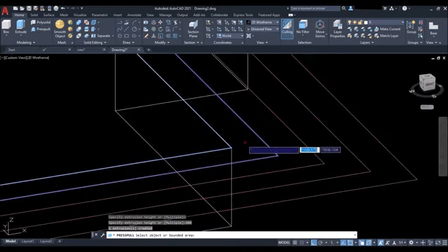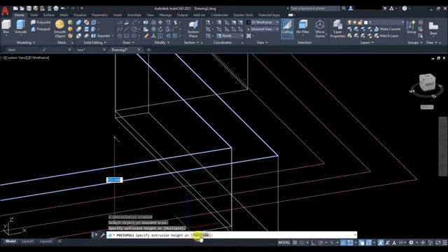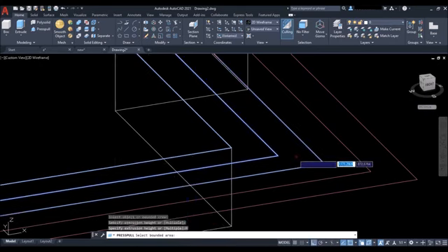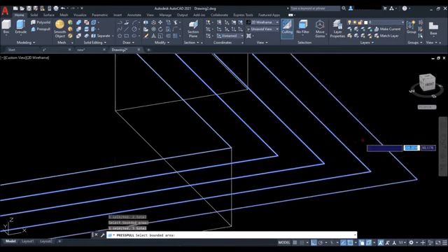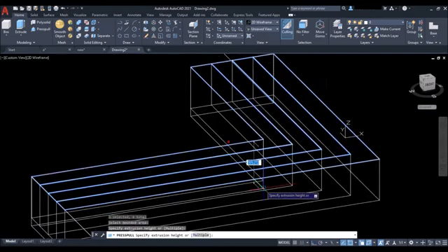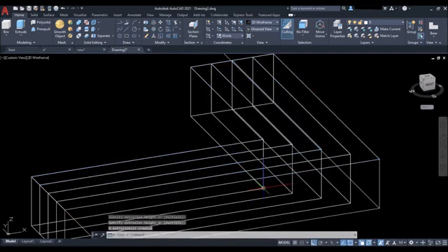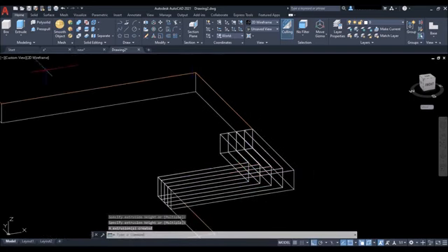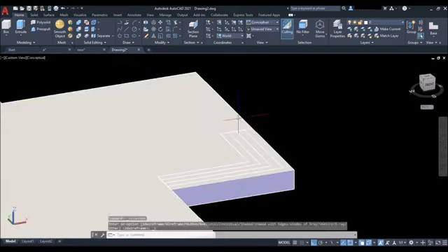Then click inside this boundary, click on multiple in the command line. Then click inside the boundaries as shown. Never ever click on the lines, press enter. Then click at this snap to press pull this downwards by 600 as well. Change the visual style to conceptual.